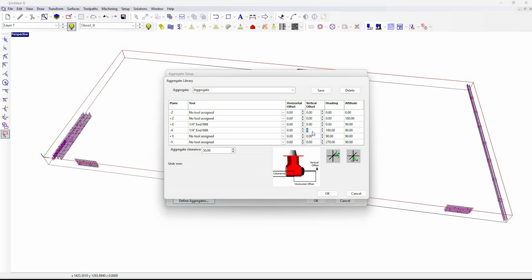When the offsets are left at 0, the coordinates that EnRoute outputs will be those of the toolpath itself. This will work great for the machine that we are currently outputting to, because the offsets are accounted for by the device. Should this not be the case, we would have to enter the offsets here before generating the output.